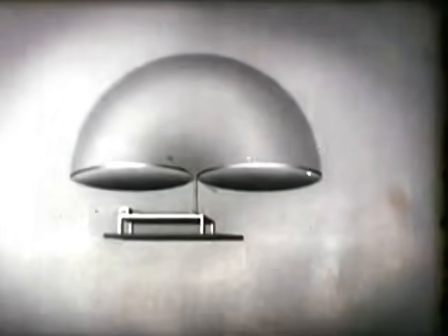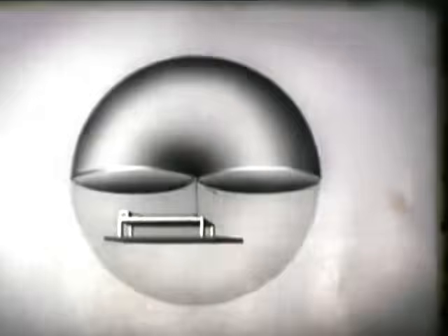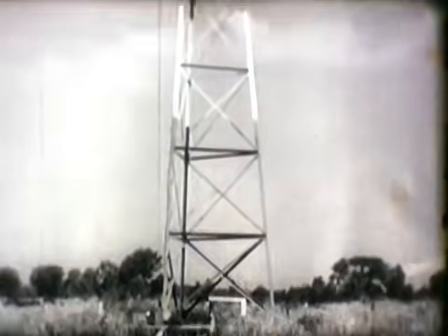A three-dimensional representation of the pattern looks something like a donut. Regardless of its physical length, any half-wave antenna will radiate this type of pattern. A half-wave antenna should measure half the wavelength of the frequency employed. This broadcast antenna measures approximately 309 feet.